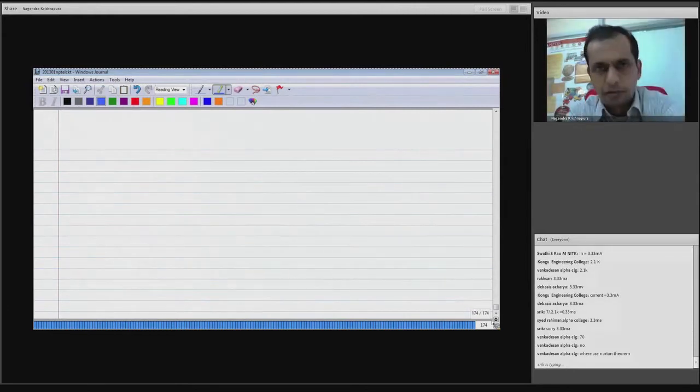You will get, with the Thevenin or Norton equivalent circuit, which is very simple, the equivalence of the circuit at those two terminals. You will not get an internal picture of what is happening, but at those two terminals, the behavior of voltage and current will be equivalent to that of the original circuit.